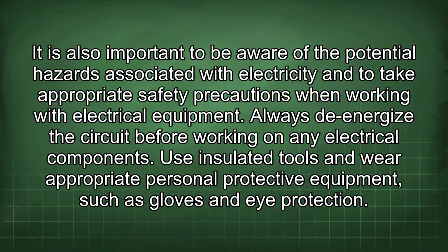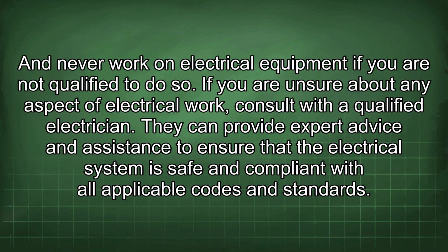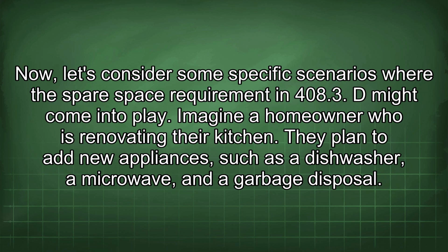Always de-energize the circuit before working on any electrical component. Use insulated tools and wear appropriate personal protective equipment such as gloves and eye protection. And never work on electrical equipment if you are not qualified to do so. If you are unsure about any aspect of electrical work, consult with a qualified electrician. They can provide expert advice and assistance to ensure that the electrical system is safe and compliant with all applicable codes and standards.